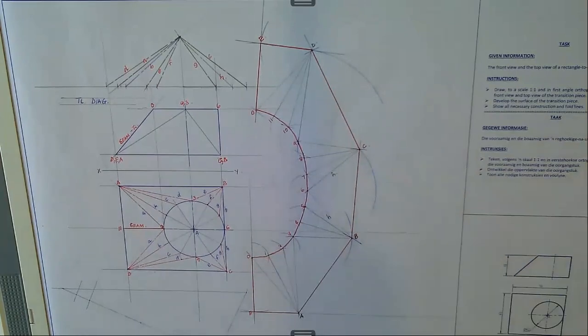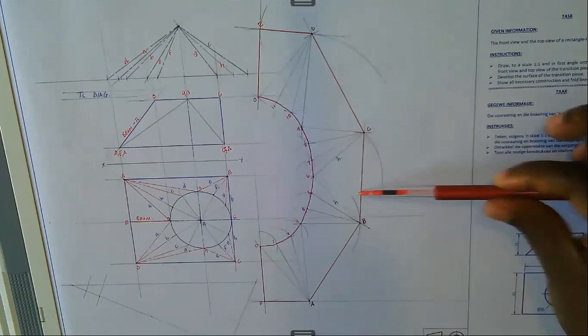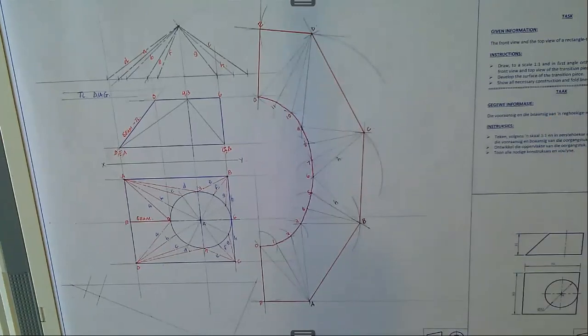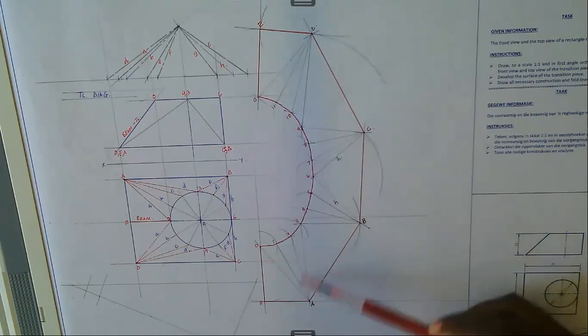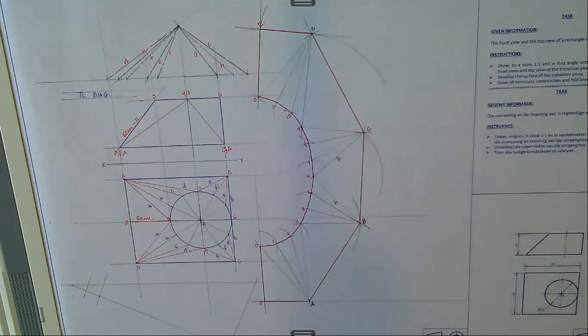There you go. Right. So if we are going to cut the material which should be used for the development of this transition piece, this would be the pattern, this would be the template. So you cut it accordingly, according to this true size. These are the 4 lines, they should be indicated, which define a series of triangles. Right, just like we did with the last exercise.